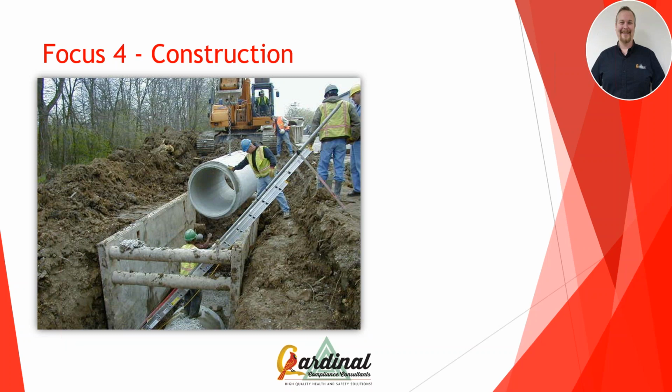How about caught in between? What if that pipe was to fall and it didn't hit that gentleman, but it was able to roll and pin in between the trench box and the pipe itself? We have a lot of potentials here for fatalities, for serious injuries.